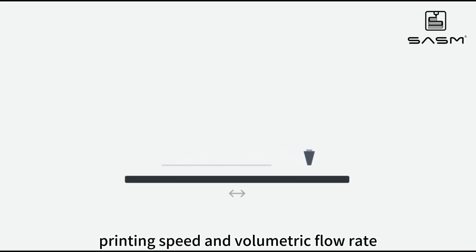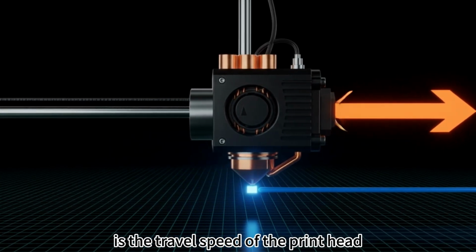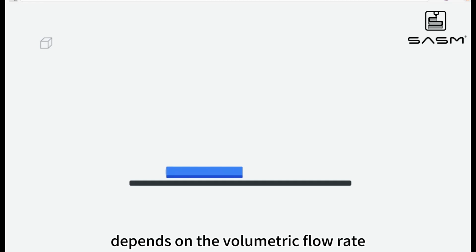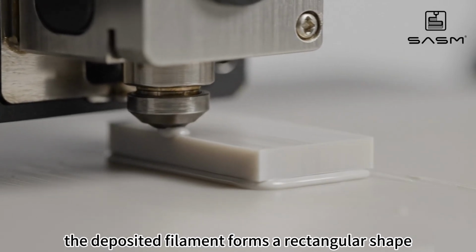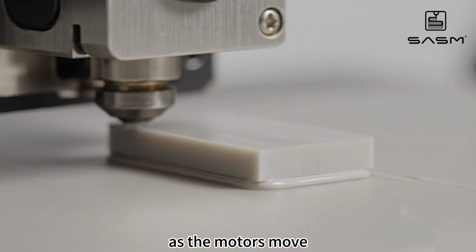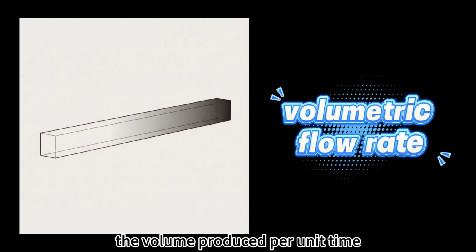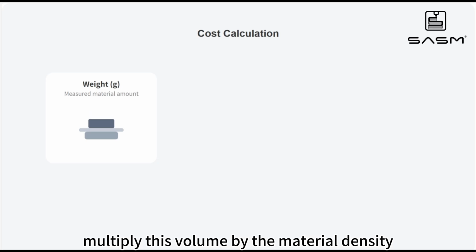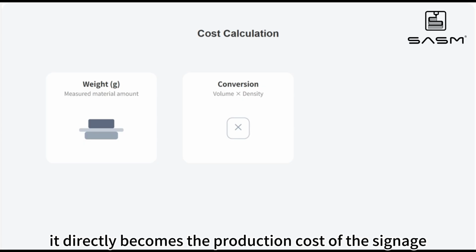Printing speed and volumetric flow rate. What we usually call printing speed is the travel speed of the printhead driven by the motors. However, real production efficiency depends on the volumetric flow rate. As mentioned earlier, the deposited filament forms a rectangular shape in cross-section. As the motors move, it is stretched into a rectangular solid. The volume produced per unit time is the volumetric flow rate. Multiply this volume by the material density to obtain the filament weight, and when converted into grams, it directly becomes the production cost of the signage.